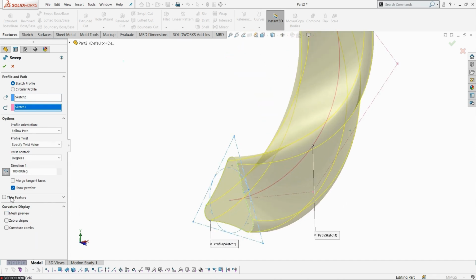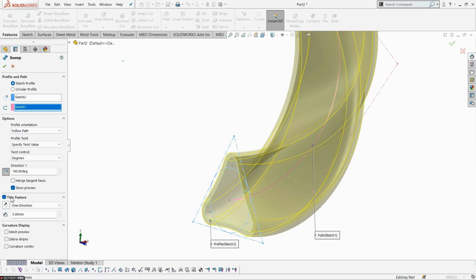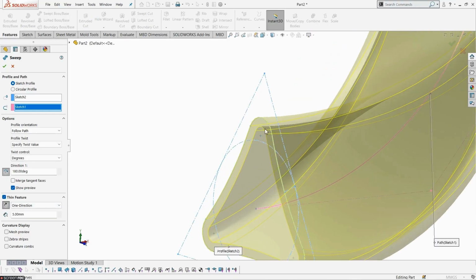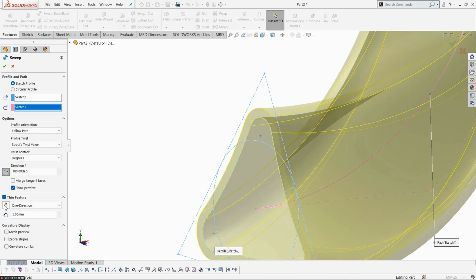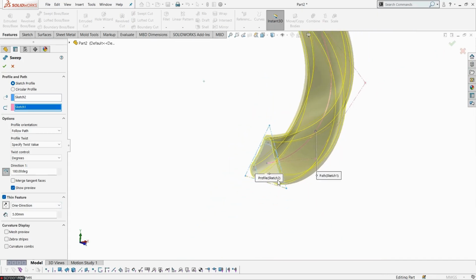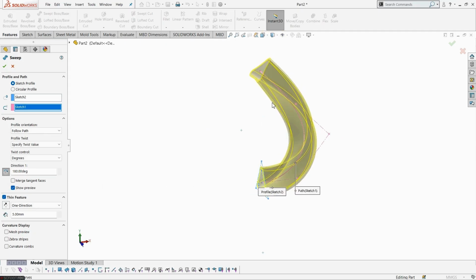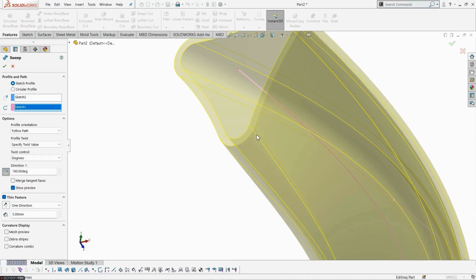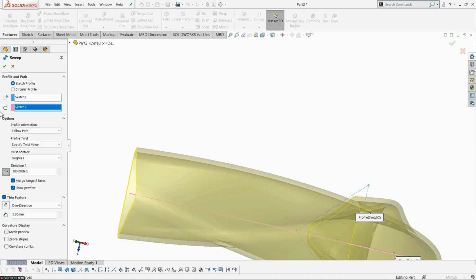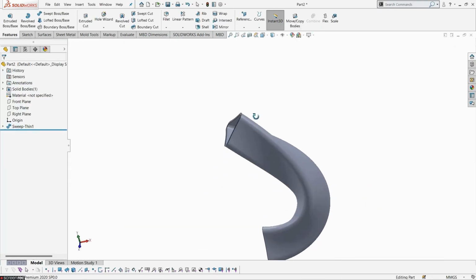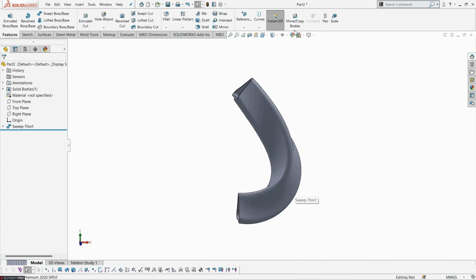Then go to mesh preview and select the thin feature section. Afterwards, just change the values. Change the direction of it now. The opposite dimension is 5 mm. Once it is properly specified, the perfect body gets created. That is the overall twisted portion as well as the thin feature formation. Now the twisted body is created at the right position.